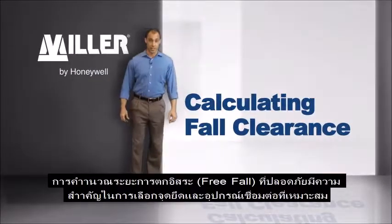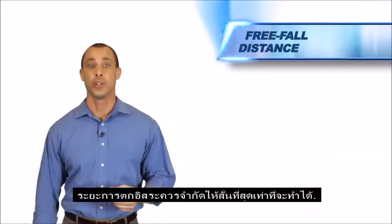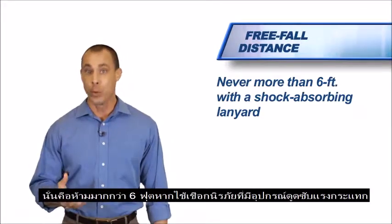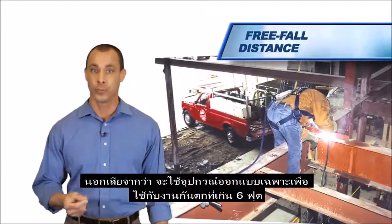Fall clearance calculations are vital in selecting proper anchorage points and connecting devices, and to avoid striking a lower level or obstruction in the event of a fall. Free fall distance should be limited to the shortest distance possible. This is never more than 6 feet when using a shock-absorbing lanyard, unless using equipment designed specifically for free falls over 6 feet.